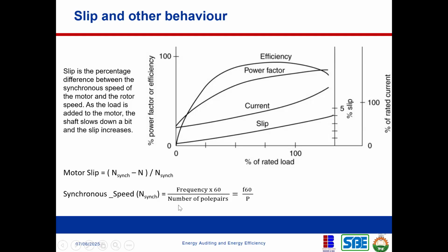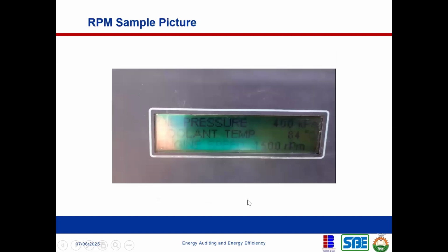All right, noted. So in some given instances, if you look at the data sheet of that motor and you see that the pole number is 4, what you're essentially going to put here, what you're going to be dividing by, is 2, because you're pairing it. If you're given that the pole number of that motor is 2, then you're going to put 1 here. So if you translate that into the formula, it becomes frequency times 60 divided by the pole pairs. Now let us see a worked example.